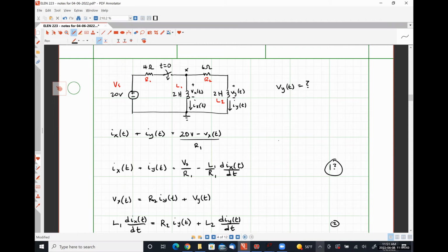But definitely explore those types of things when you're doing your homework and working on the take-home portion of your exam. The two circuits that we have analyzed happen to work well with doing KCL at that top middle node and KVL around the right-hand loop. That's not always the case. So any KVL expression should be valid and can be used. Any KCL expression should be valid and can also be used.